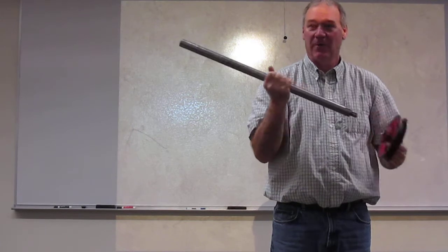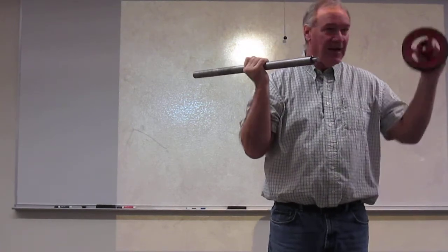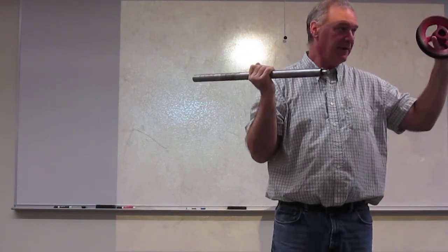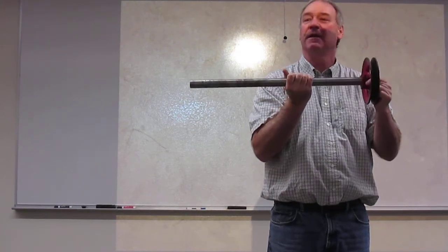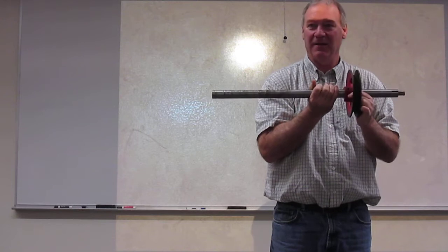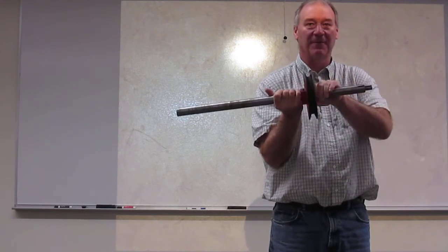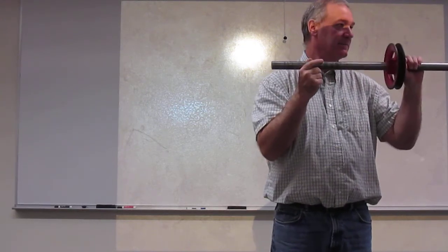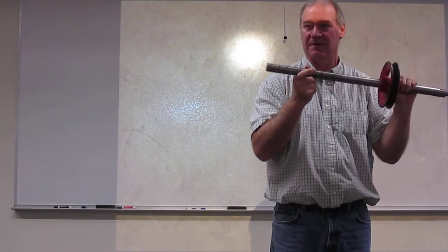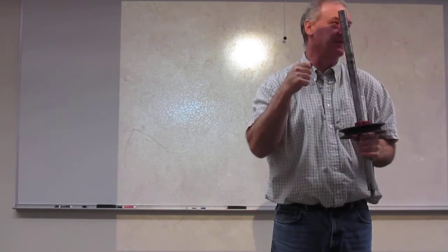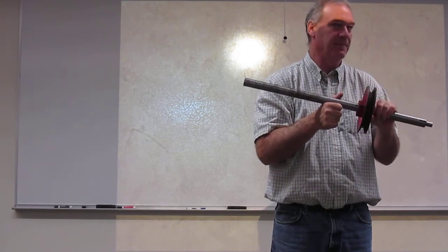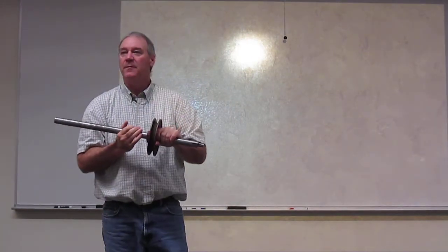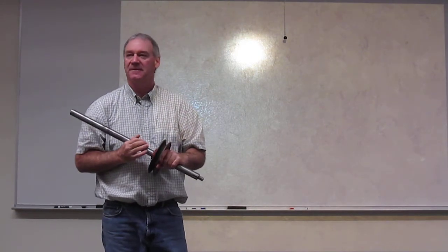Many times we might build this to where it never fits in this and it's a joining method. I have to use presses, so I would take this and shove it in there with some machine so that it removes material from both of them. Now it's joined on. Now, those of you that have worked on your cars and you see bearings that you have to use pullers on, that's how they're constructed. Holds them together. We can have a lot of different methods, but that's how we join them. We always look at allowance. That's the first thing we look at.